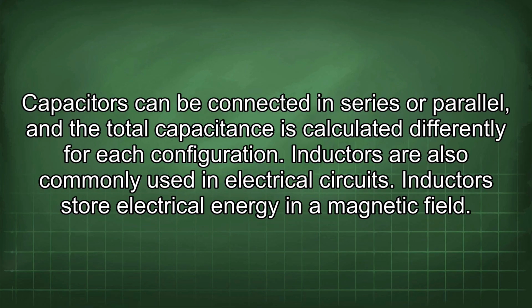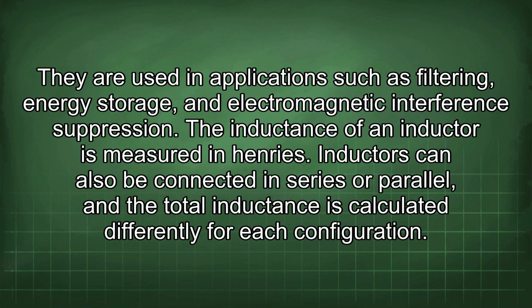Inductors are also commonly used in electrical circuits. Inductors store electrical energy in a magnetic field. They are used in applications such as filtering, energy storage, and electromagnetic interference suppression. The inductance of an inductor is measured in henries. Inductors can also be connected in series or parallel, and the total inductance is calculated differently for each configuration.